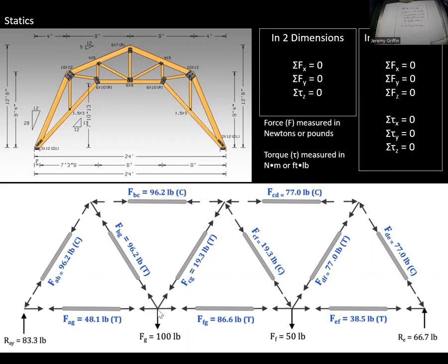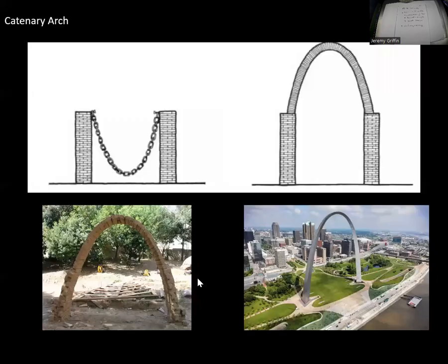Okay, so then do like a cutaway. I might pick this point of this truss system and figure out what's the compression and tension on each part. And then furthermore, if you know what materials you made this out of, you say, oh, it looks like the compression on this part is more than the maximum compression of the concrete we're building. We better go back and redesign that part of the truss system, something like that. There you go. There's statics.